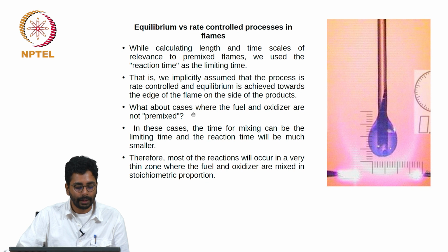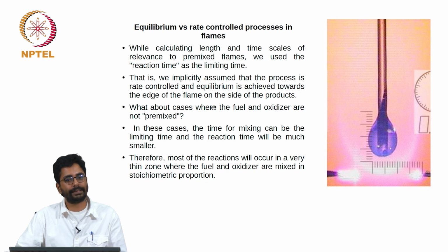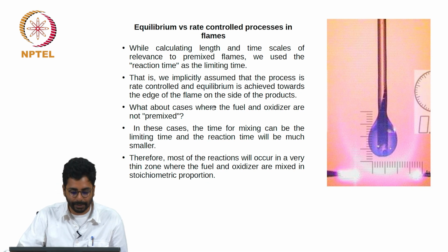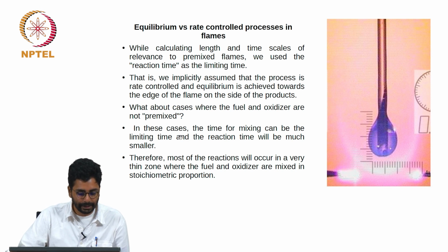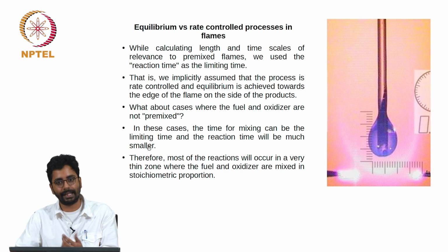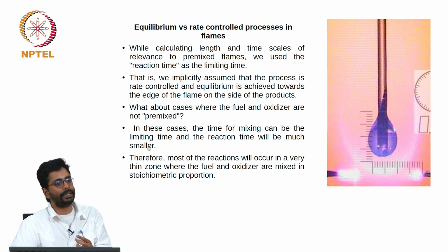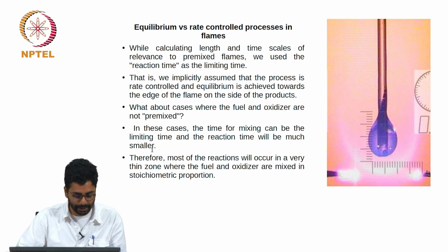But of course there are a lot of cases in reality where the reactants are not premixed, for example, the droplet flame that you see on the right. In these cases the time for mixing can be the limiting time and the reaction time will be much smaller. In fact, in this case the time for mixing is also not the limiting time, it is the evaporation time that is the limiting time.